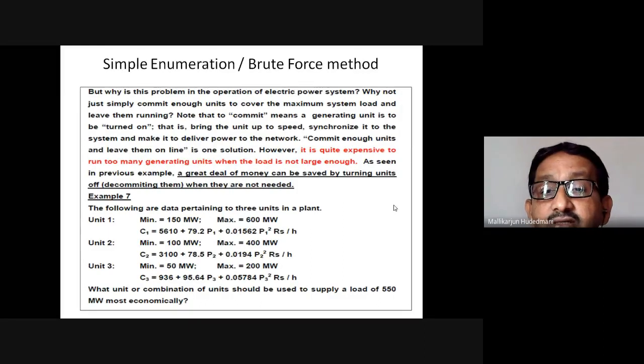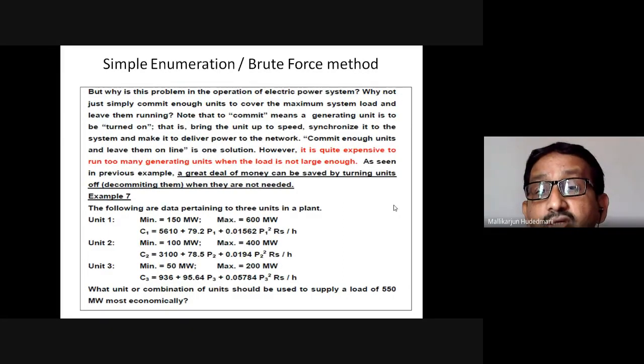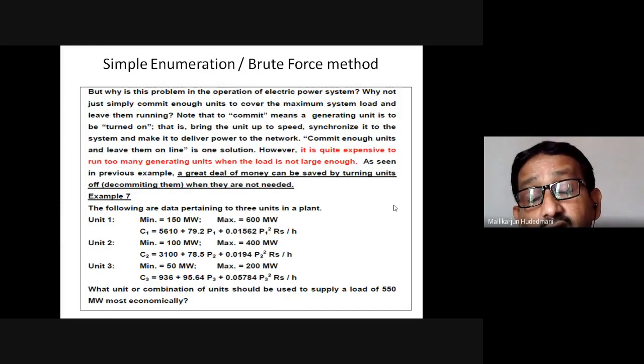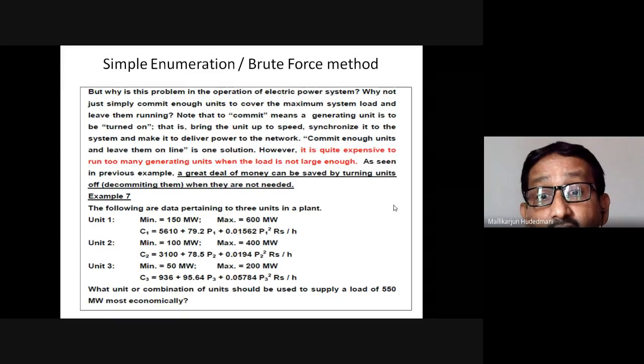So there is a small difference in approach compared to economic scheduling, which finds an optimal megawatt on each generator using the whole set of generators in combination. That is what Lagrange's optimization mechanism we have learned. In unit commitment, we will not be taking that.